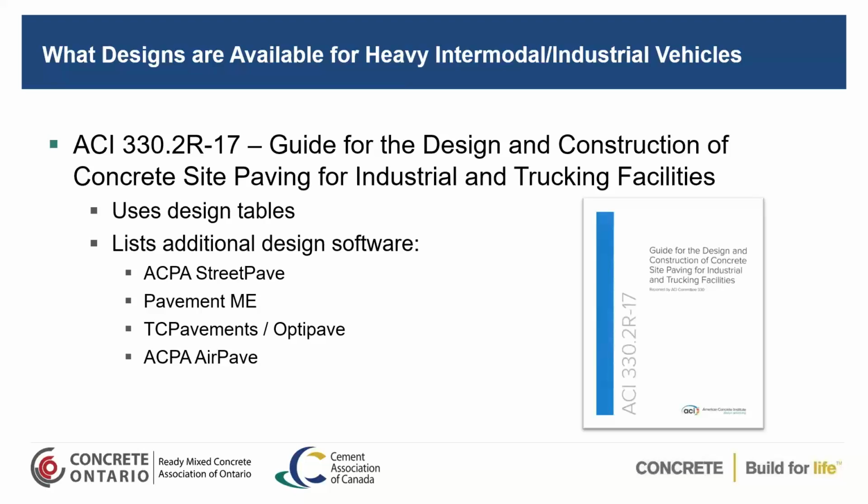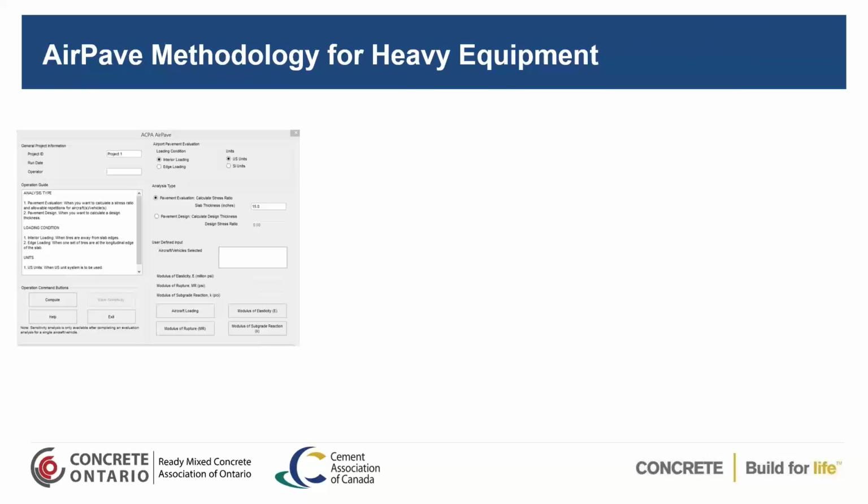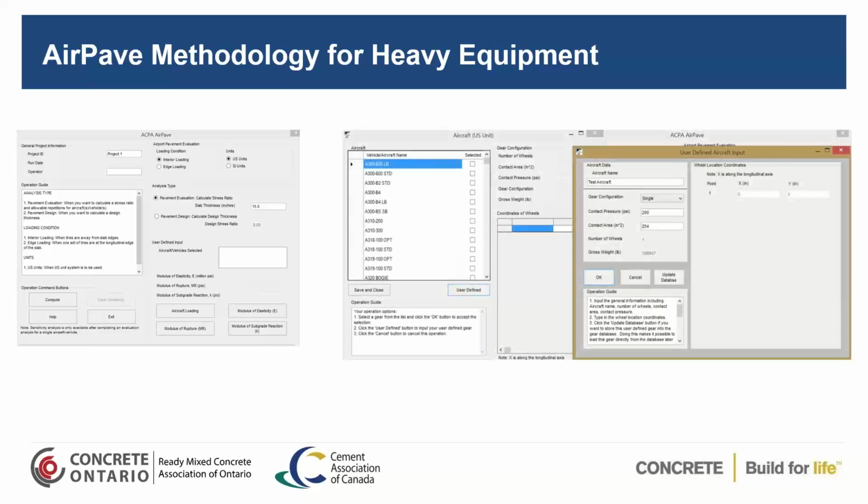Now, talking again about heavy intermodal or industrial vehicles, the ACI guide gives some guidance on that as well, and AirPave. The AirPave software allows you to input your normal inputs like the resilient modulus of your subgrade, the flexural strength, and the modulus of elasticity. What you actually have to put in, unless you have your vehicle that's part of the provided